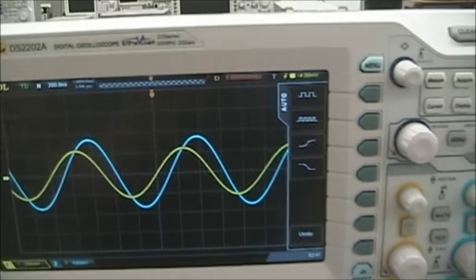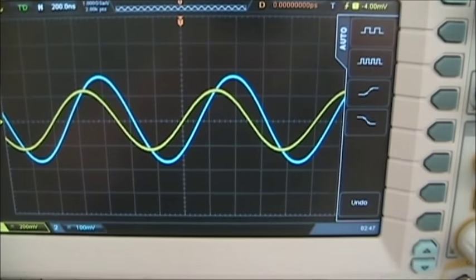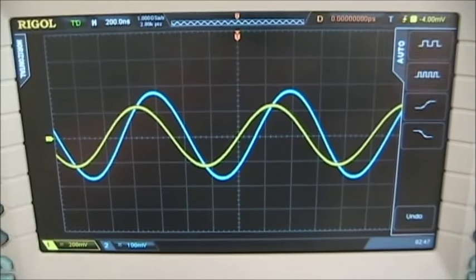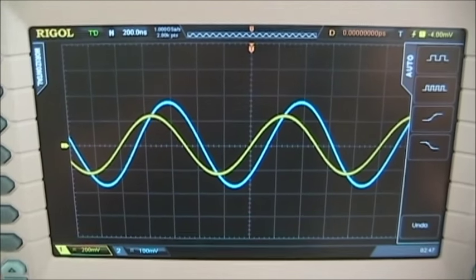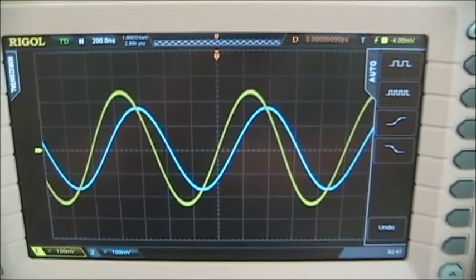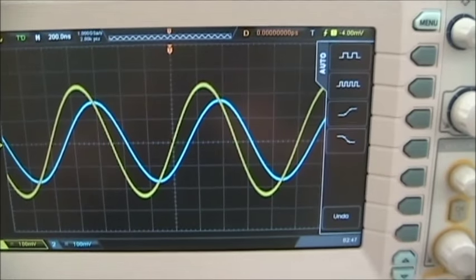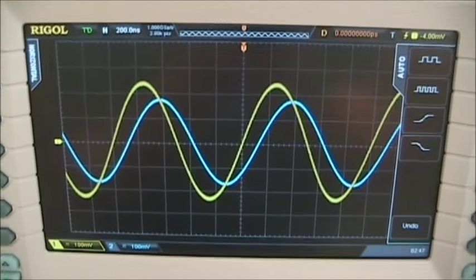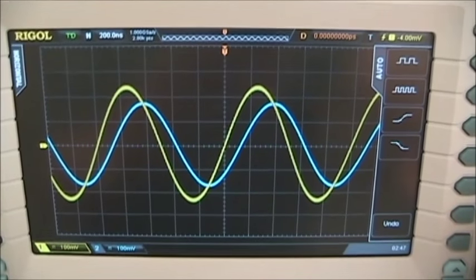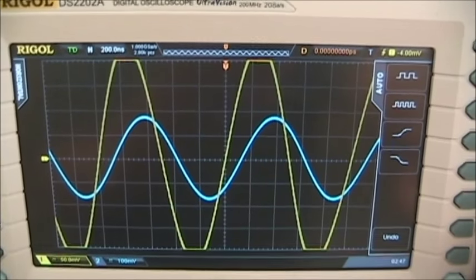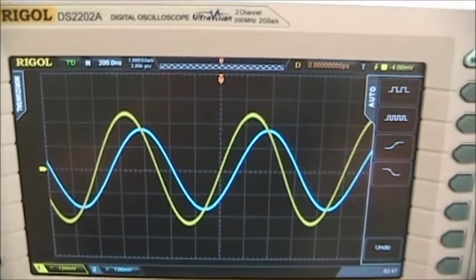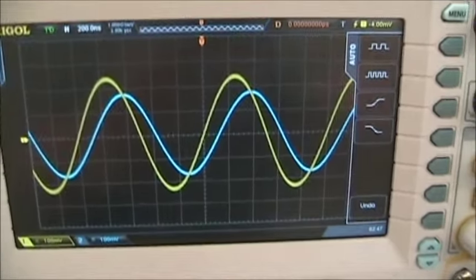That's particularly useful for making phase type measurements. Whenever you make a measurement on the scope, you should adjust the values such that the signals are at least 1/2 the screen size, and that is good for resolution. If I go any lower, it overranges. We don't want to do that. So we've set that out.